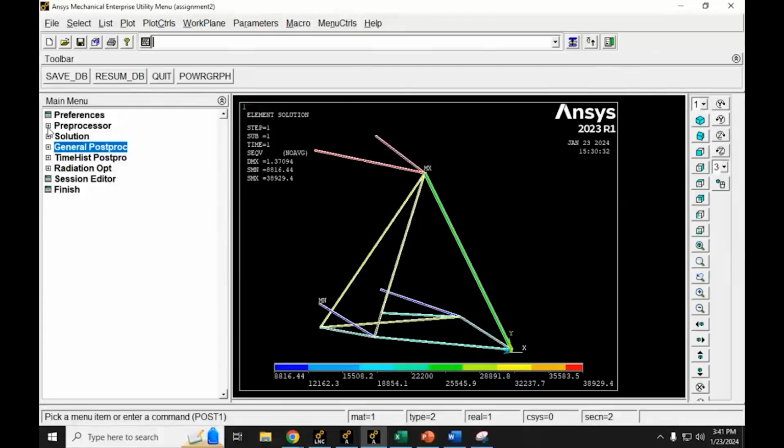And then if we had a similar plot of displacement, say displacement is x, we want to look at time equals 0, how the structure responds to this applied load. It's going to do something like this, right? It's going to oscillate. As soon as you apply the load, it's not going to instantaneously hit that deformation. It's going to take some time. And there's no dampening in the system, so it's just going to ring forever, basically.